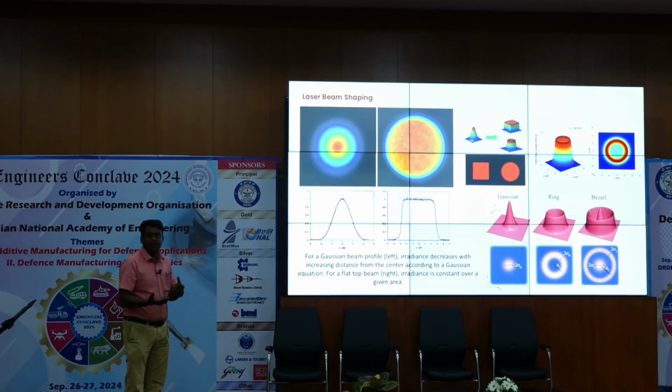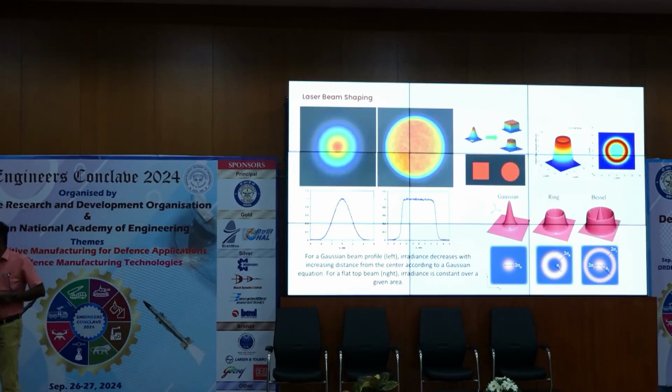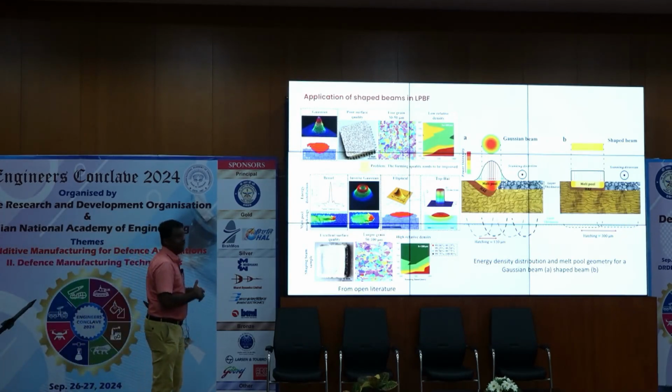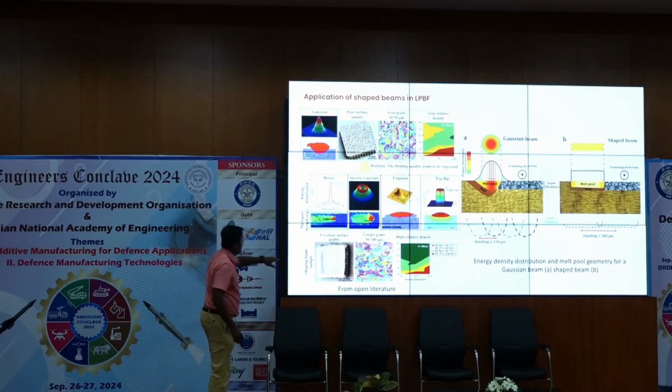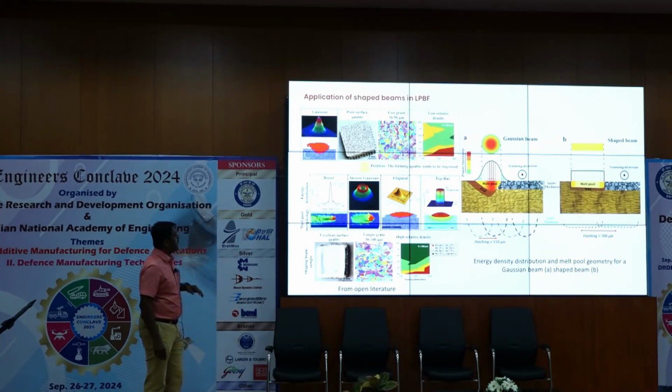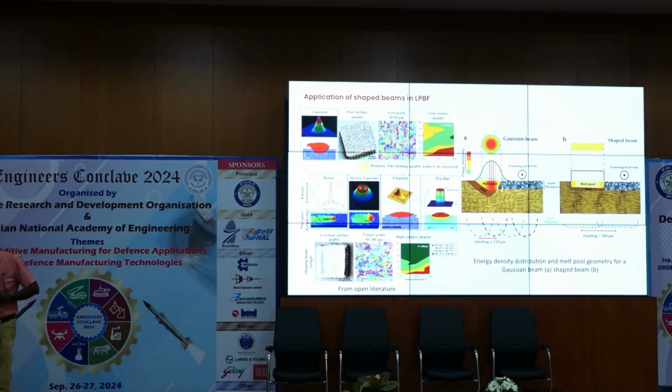Okay, so they also apply beam shaping from Gaussian beams to flat, vessel, or donut shaped beams. For example, you see in the middle, ring shaped beams are ideal for a DED process where coaxial feed of wires can be effectively used. But then how do we implement this? There are multiple literatures, people are attempting this all over the world and in India. When we started this work, it was impossible for us to do that. But people have been showing, for what you see here, the microstructure and post-surface quality with the Gaussian beam, and the same sample when printed using a flat beam shows an excellent surface finish improvement, and we can also control the microstructure. Why? Because of the melt pool shape and the power distribution in the melt pool, what you see here.